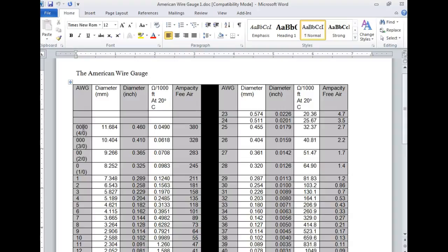If you ever watched the Beverly Hillbillies years and years ago, Jethro called zeros aughts. So aught is another name for a zero. So we would refer to this as a 4/0 conductor. And it has a diameter of 0.46 inches, which would be a little less than half an inch. Yeah, probably, no, it's still not a half inch. Half inch would probably be, what about right there? So this guy here has half inch. And that's as far as American wire gauge goes. Above that, we actually use something we call kcmils, which we'll look at in a minute.